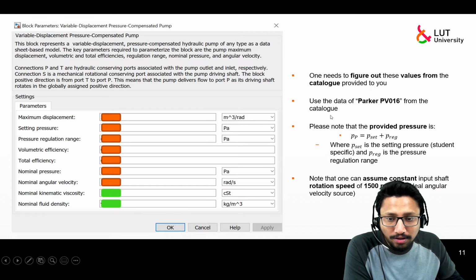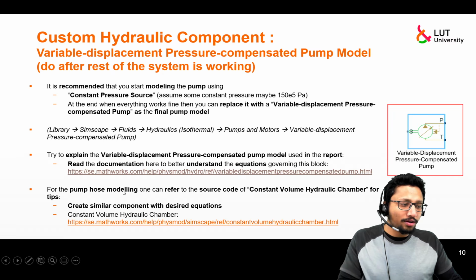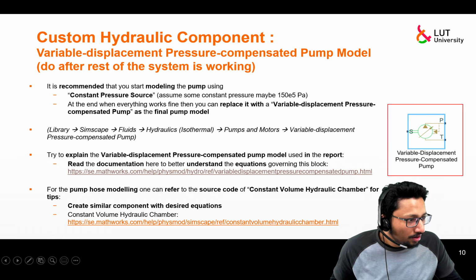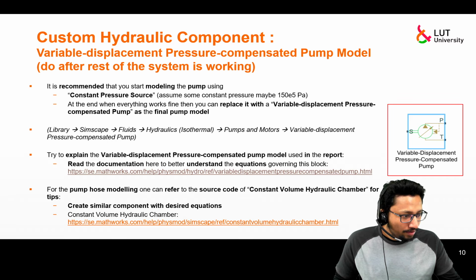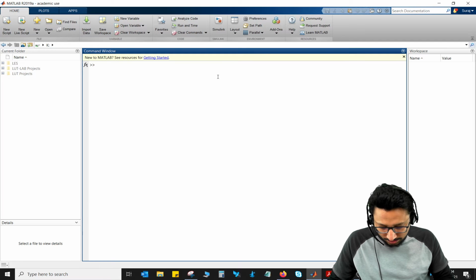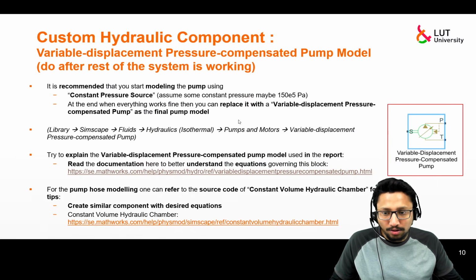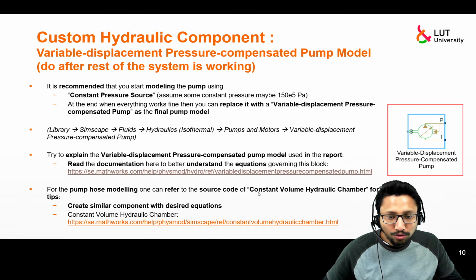Once you have modeled the pump carefully, you need to also incorporate the pump hose modeling, right? So I would suggest you look for the source code of this constant volume hydraulics chamber. If I go to my MATLAB and type smnew, it will take a while. Let it open. So we will see the pressure source code of this one,